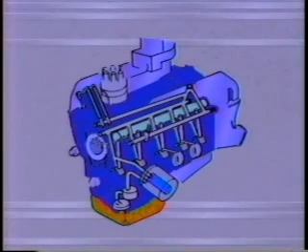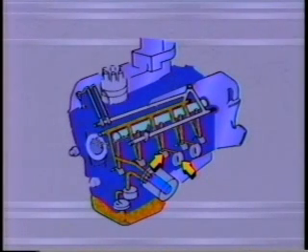But I'm confused about all the different engines. There's overhead cams, dual overhead cams, rocker arm shafts. There's all kinds of differences. Well, those are good points. But what you've got to remember is that typically there is a basic feed pattern. Now, here's the basic feed pattern. Oil pan to strainer, to pump, to filter, to bearings is pretty well set and won't change much between engines. It's the upper part of the engine where you'll see differences.